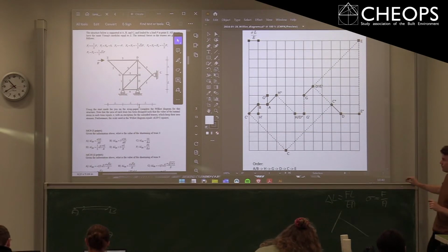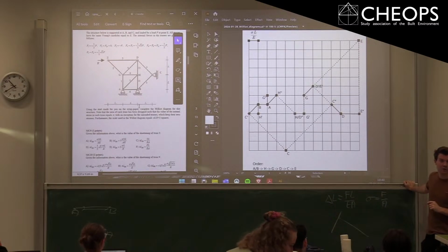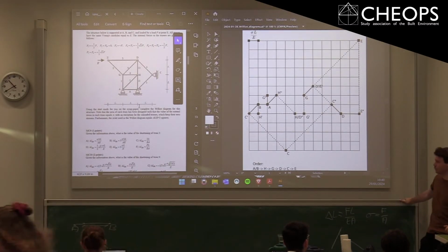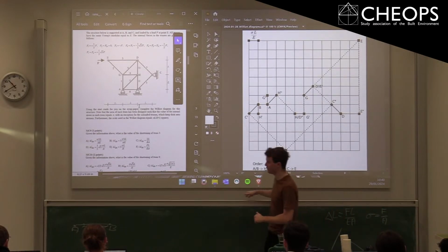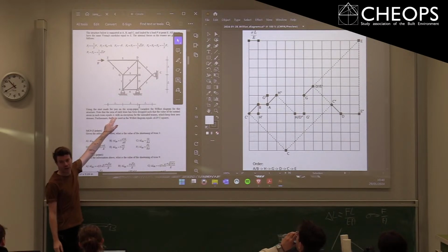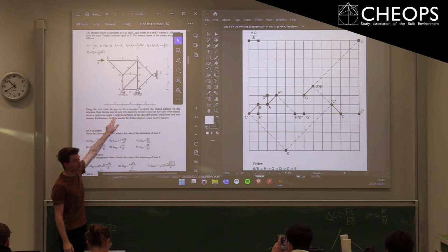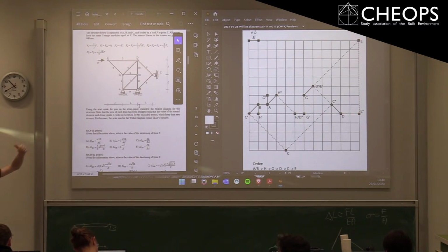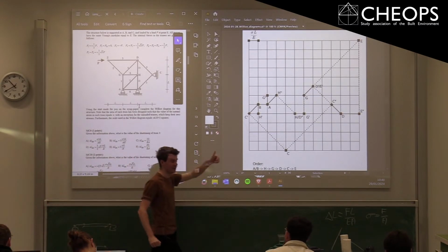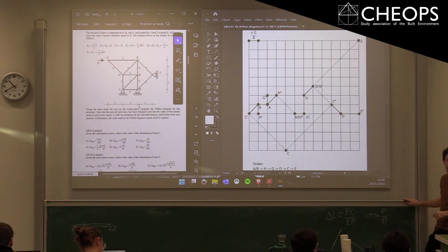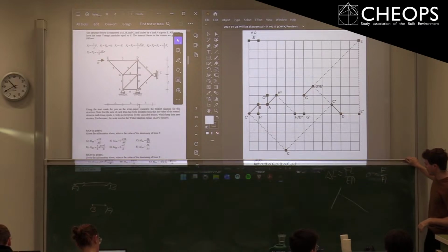Okay, I will quickly go over that second Williot exercise. There is a very important distinction, and you have to look for that before you start these kinds of questions. It was this part, right? Where they state that in each member the stress is going to be sigma, just a constant. Remember from the previous one, they gave you the area of each member as well, like the diagonals had the square root of 2 area.